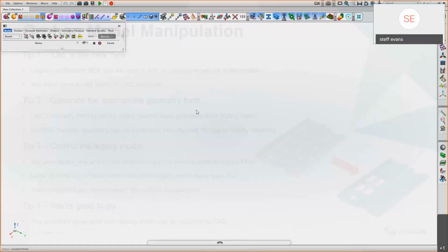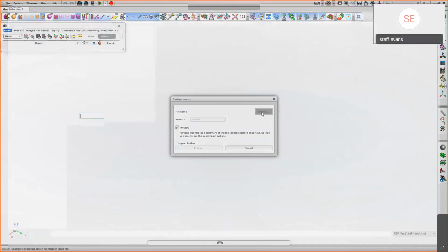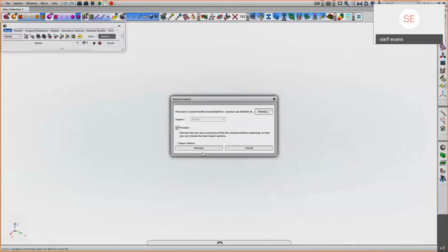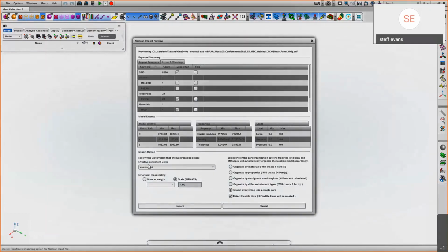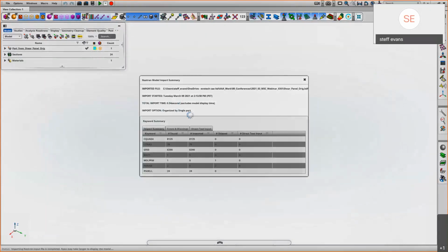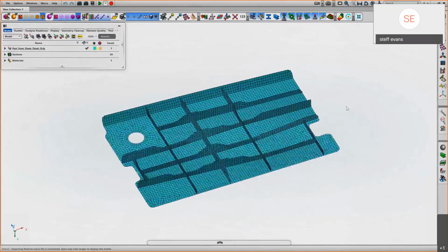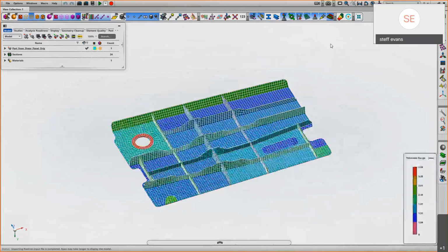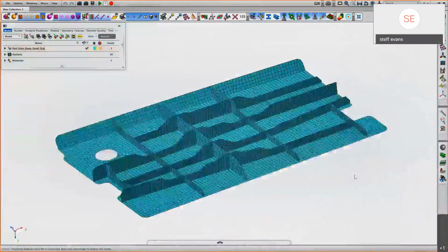Okay, so just running through the last demonstration example that we've got. So again, bringing in a model now. So no geometry, just cycling through to the bulk data format definition, bringing in the BDF file. So we set the model units, so millimeters, a millimeter model in this case. The entities come in, and we can see we've got the mesh definition in there. We've got the shell properties defined, and we can start to play games with this.